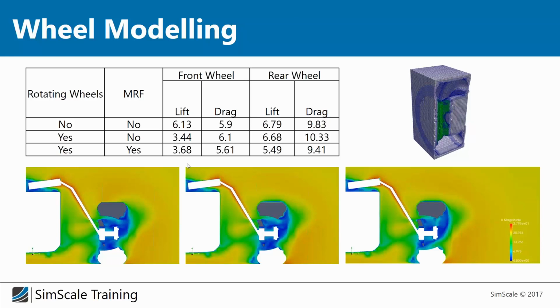Okay, then we have some more questions. Bart wants to know if the software only uses mass and momentum equations for computation. This depends on what you're simulating. If you only do a so-called cold flow simulation, where you assume that the changes of temperature and density are so small that you can neglect them, then yes, you don't need the energy equation. But if you want to do CHT or also investigate how heat is transferred inside the fluid, then we use another model where we have 3 equations, including also the energy equation.